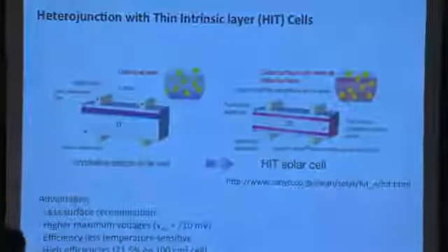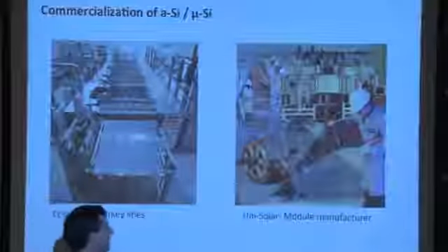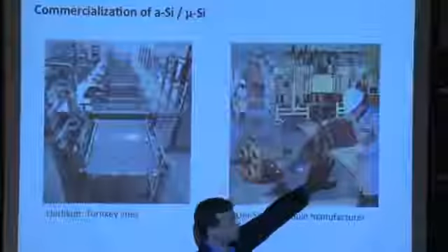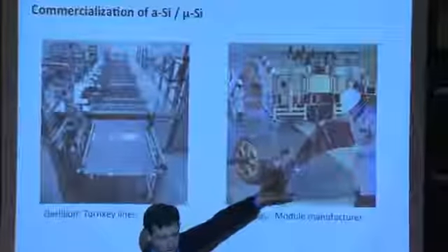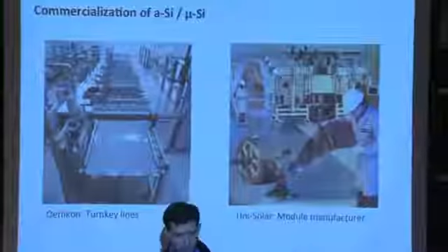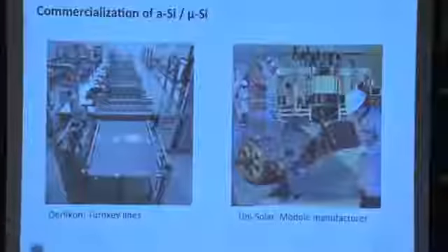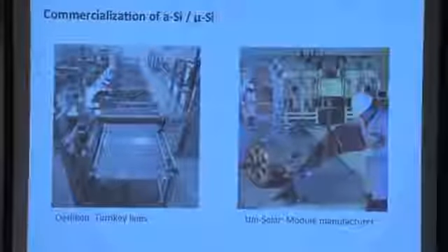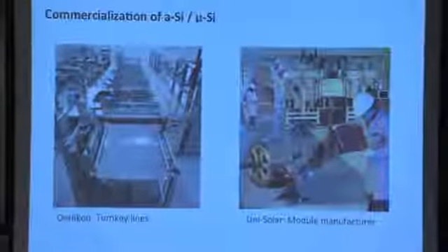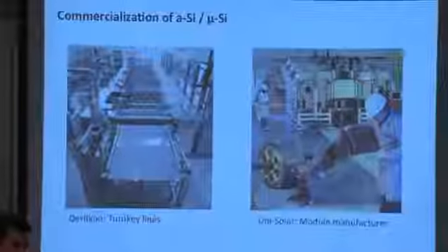Is the roll that that person's holding, what is it? What is he holding? I could easily think, based on the color, that this already has amorphous silicon deposited onto it, but it could be at some intermediate phase. I don't know for that specific roll. But in principle, yes, at the end of their manufacturing line, they'll have a full stack, the triple amorphous silicon and then the 2 layers of SiGe beneath it.